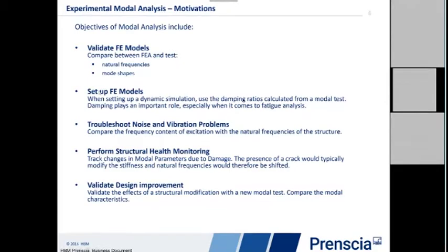And then when it comes to doing some force response or dynamic analysis in FEA, whether in the time domain or frequency domain, at some point you're asked to enter the damping ratios you want to use, and most of the time, people leave the default values or don't necessarily worry about those.